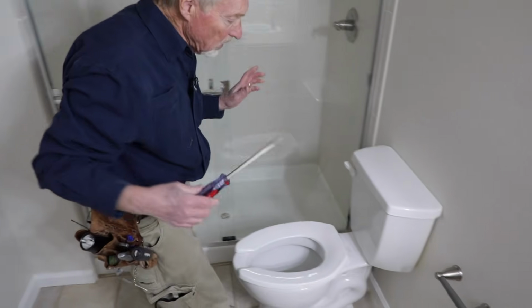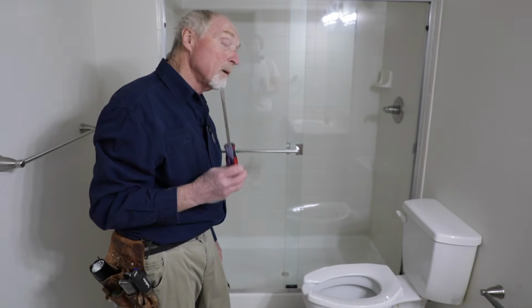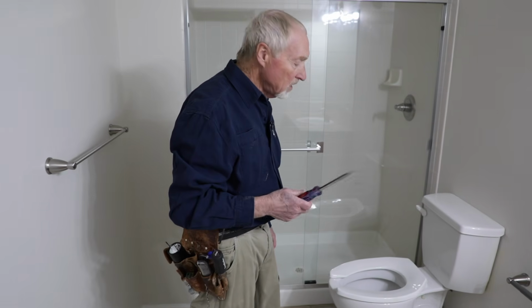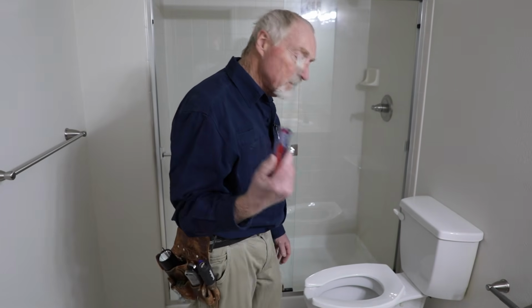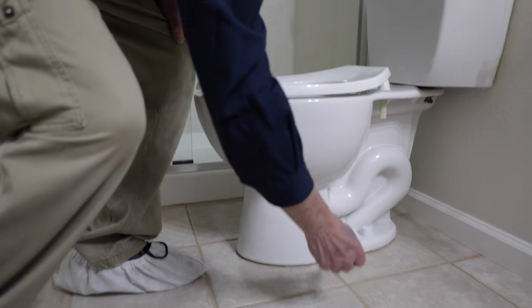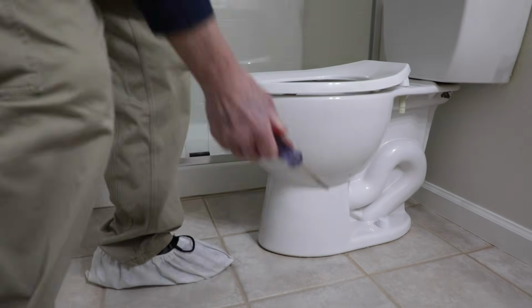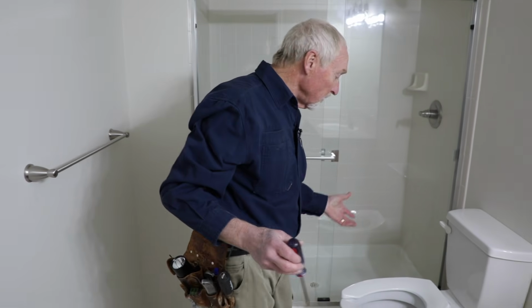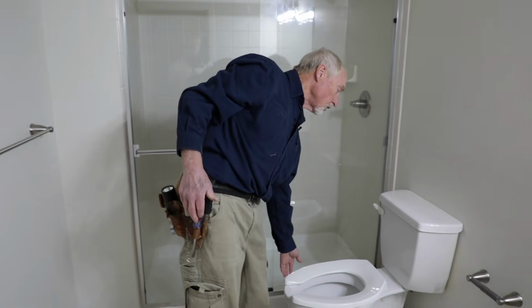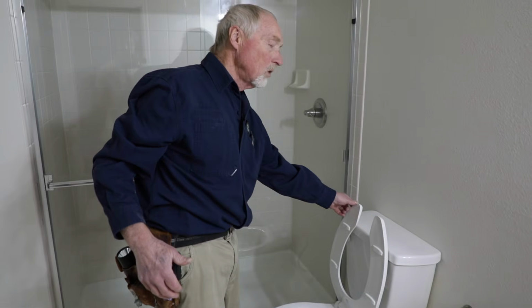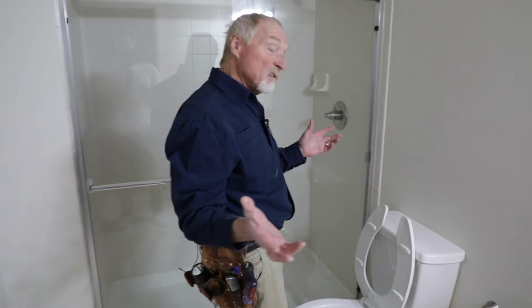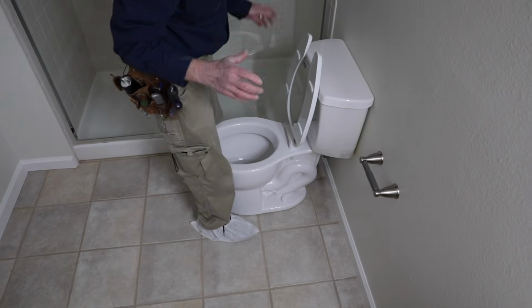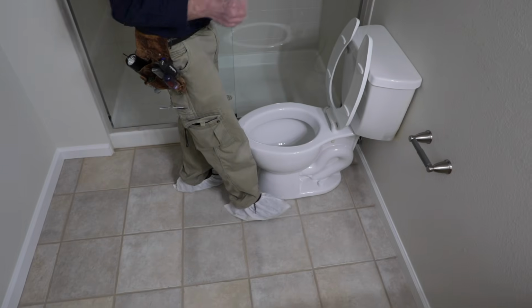One thing, toilets are supposed to be sealed to the floor, and by the way, that means sealed completely around the base. And an easy way to check that is to take my screwdriver and go around the edge. I don't have any caulking there. Oops, that's a mistake. We would recommend sealing. And another little trick for checking to see if the toilet is tight to the floor, because you don't want to use your hands on it, just put it between your legs and rock back and forth and see if it moves. If it doesn't, and this one didn't, good.